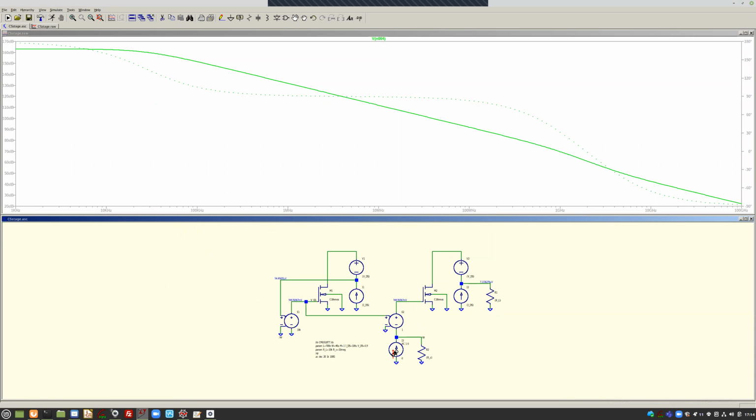And this looks, of course, like the transimpedance, because we have current and the source impedance is very high. It's like 10 megaohm. So setting a limit here, but basically if I make 10 megaohm larger, we would get a real integrator there. So this is basically the first pole that should be in the origin if I was driving from an ideal current source. But that is difficult in SPICE because then this current is flowing into a floating node, and that is not allowed. So anyway, you need to place a resistor there, maybe 1 teraohm if you want. And here you see a second pole and a 0.